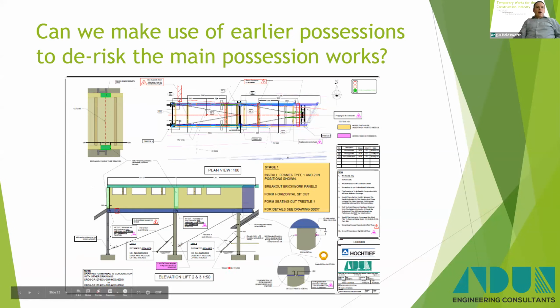We also put in temporary restraints for the other 2 spans that went back down the structure, and planned to use the same basic principle on the other 2 pieces that had to be lifted out. And then the steps and that last pier were just demolished piecemeal in situ with a Brokk.